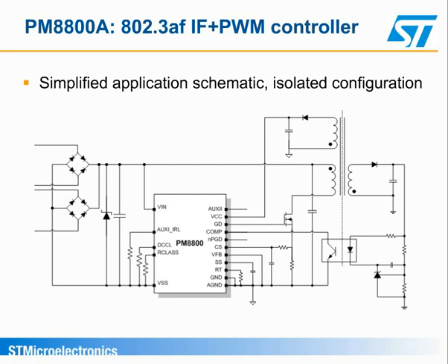In the startup phase, the internal high-voltage startup regulator outputs an 8-volt reference. As soon as the DC to DC converter reaches regulation and the auxiliary winding of the transformer provides a voltage higher than 8 volts, the internal regulator is switched off to save power.